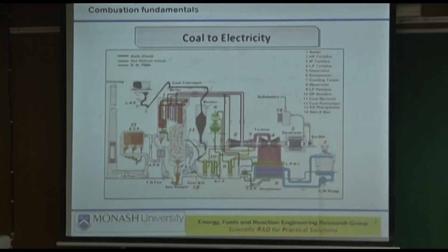Okay. So it's actually an irony. The lower rank coals are more reactive than the higher rank coals, simply because they still haven't become mature. It's like a young kid, you can tailor it to become whatever. So brown coals and lignites are like that. They are not mature. They are somewhat unstructured, so you can train them to do whatever it is. That's the similarity, as simple as that. You cannot do that to anthracite. Anthracite will resist.